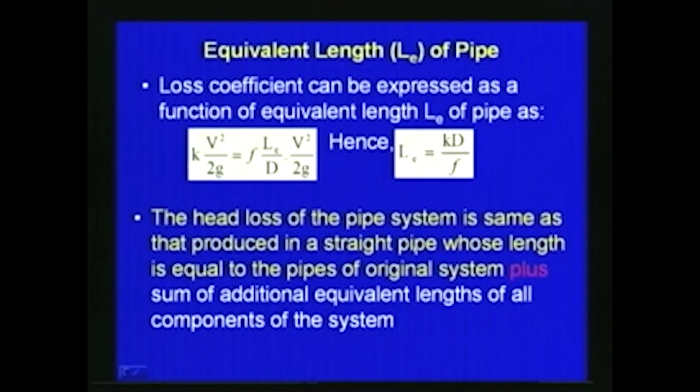So like this, for various valves, various junction T's or various gates, depending upon the type of material and the way of manufacturing, and how we make the connection between the main pipe and the valve or the fittings, this K value will vary. Most of the manufacturers specify the K value for their products depending upon the material.